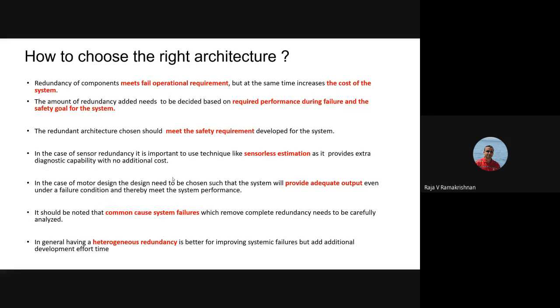In case of sensor redundancy, it is important that you use techniques like sensorless estimation, as it provides extra diagnostic capability without any additional cost. In case of motor design, the design needs to be chosen such that the system will provide adequate output upon a failure condition, thereby meeting the system performance. It should be noted that common cause failures, which remove the complete redundancy, need to be carefully analyzed. So in any system, the main problem when we have redundancy is the common cause failure.